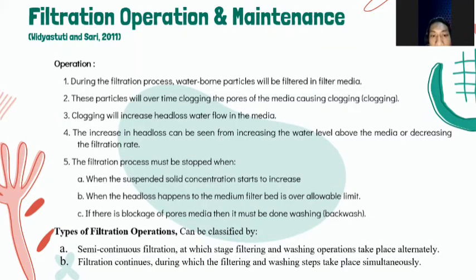Number 5. The filtration process must be stopped when A, the suspended solid concentration starts to increase. B, when the head loss in the media filter bed is over the allowable limit. C, if there is blockage of the media pores, then washing or backwash must be done.